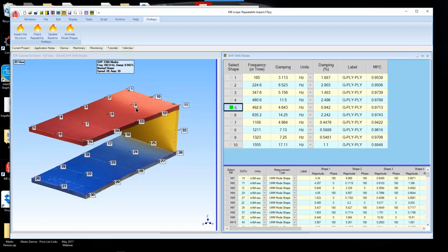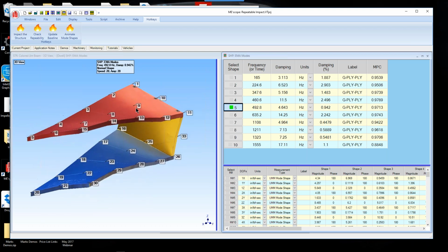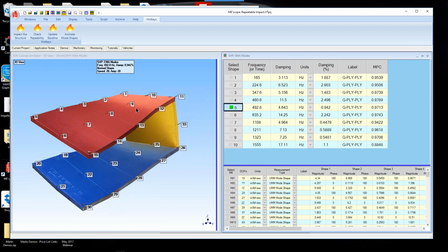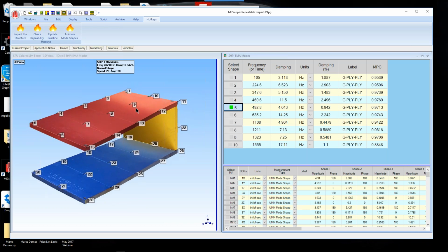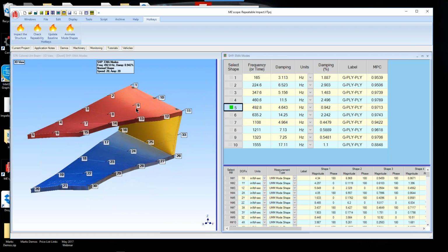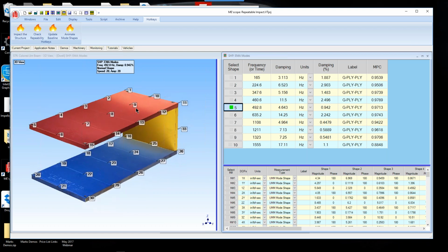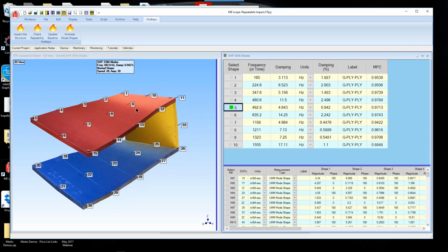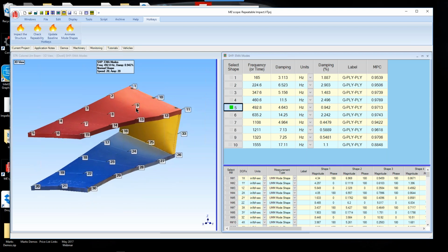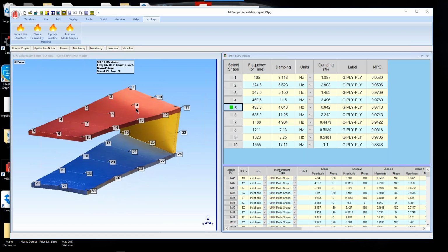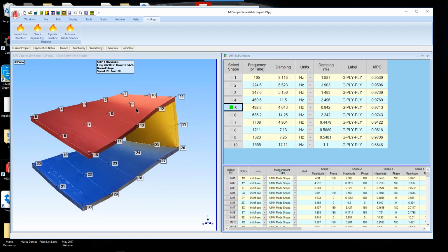The only difference is an ODS FRF gives us a true magnitude of the response, because its magnitude is the auto spectrum of the accelerometer response, versus the cross spectrum, which is the product between the reference and the roving amplitude of response. So I can't really tell how much a machine is moving if I just measure cross spectra. So let's go look at that case.